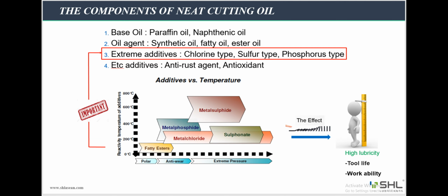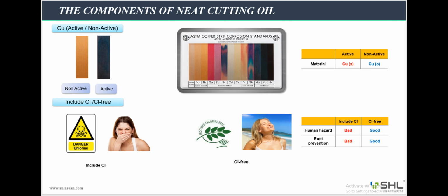Active sulfur, often sulfurized fat, provides extreme pressure properties for fluids used in heavy machining operations, such as broaching, or processes involving stainless steel and hard alloys. However, in some respects, active sulfur is sensitive in its ability to corrode metals, especially copper. From there, note when using this additive with copper materials and copper alloys.